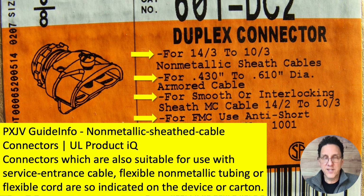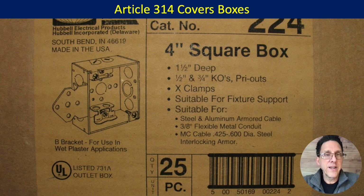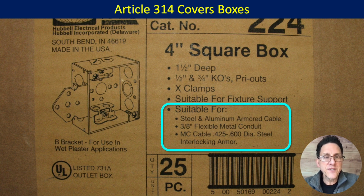Let's take a look at some other stuff. All right, here's a metal box, an outlet box. It says it has X clamps and is suitable for fixture support. Well, what type of cables can I bring into this clamp? Well, it says it's suitable for steel or aluminum armored cable.